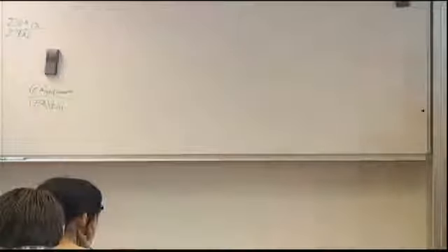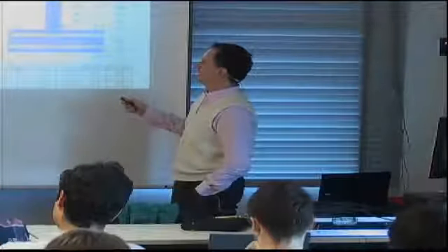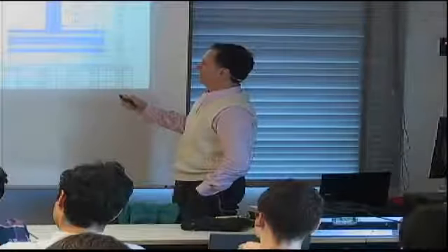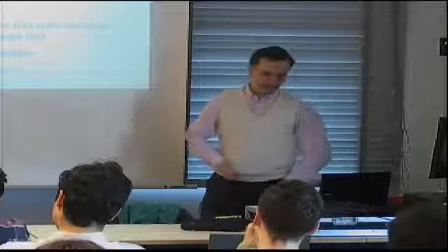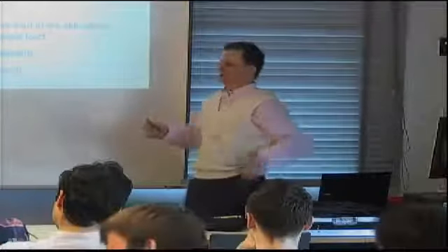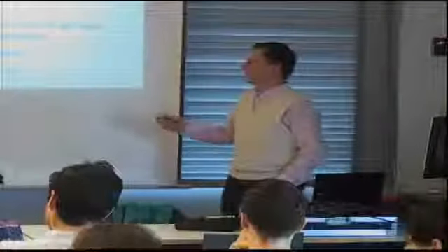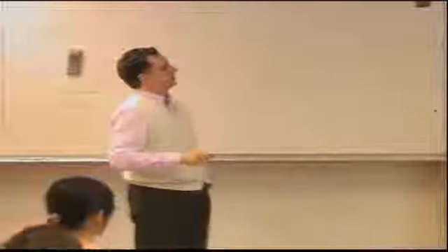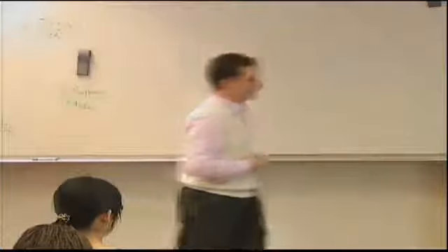Why do I divide by 4? I want to isolate each part of skin next to each stiffener just as a matter of convenience. So basically, I take a portion of the skin that is associated with this stiffener, a portion with that one, and so on. It's just a matter of convenience. That's why I have that division by 4. So each portion of skin that's near a stiffener, equally distributed, carries this kind of load. Now you can start seeing that potentially the skin will fail first because the load in the skin, due to a not so good selection of the skin stacking sequence, is 5 times the load in each stiffener.